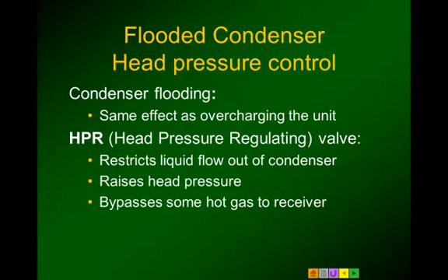And because we have to have this refrigerant flowing, the valve also then has to be designed to bypass some of the hot gas to the receiver. Now, when you bypass some of the hot gas to the receiver, that will also assist in keeping the head pressure up.